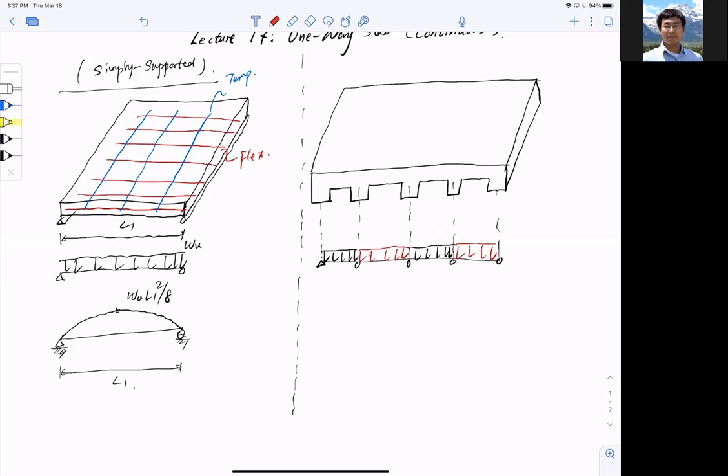If you take a look at a fully loaded span, where every span is equally loaded and you apply the maximum distributed load, the moment at the negative junction is going to be maximized, but the moment in the middle span may not be. So it doesn't necessarily give you the maximum scenario that you can take to design. We usually have to use the influence line method to determine the maximum loading on the section.